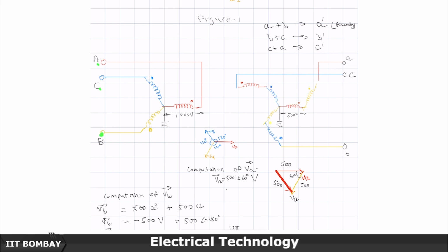balanced voltage sources here, 3 equivalent same balanced voltage sources here. So, imagine that the primary side is connected to a set of A, B, C balanced sources, and I have connected the same set, appropriately scaled, of balanced voltage sources here. Then what is going to happen is, because these currents in series cannot be phase shifted, they will have to be 0 only, that is the only right condition.